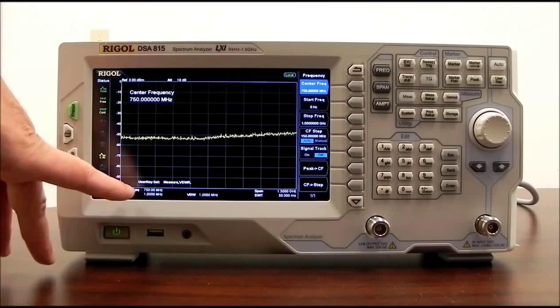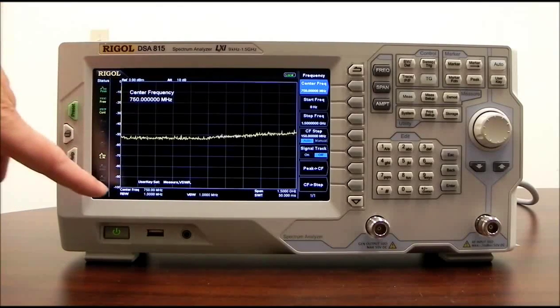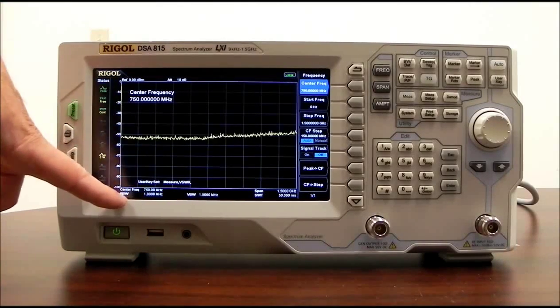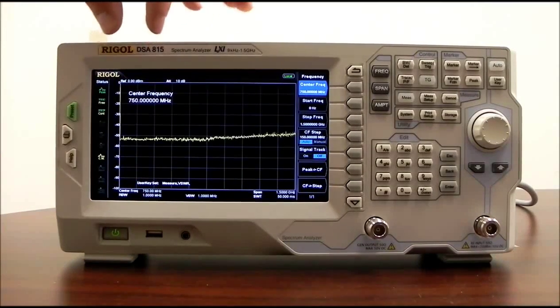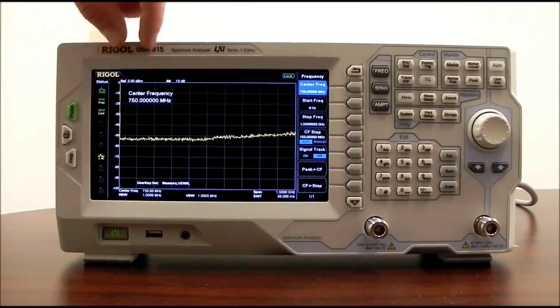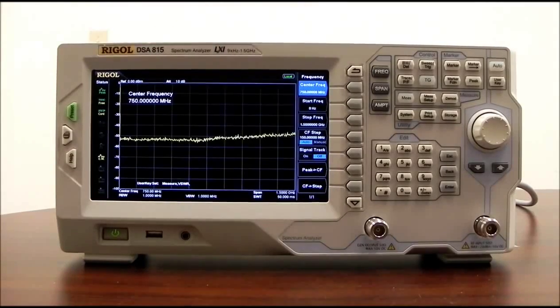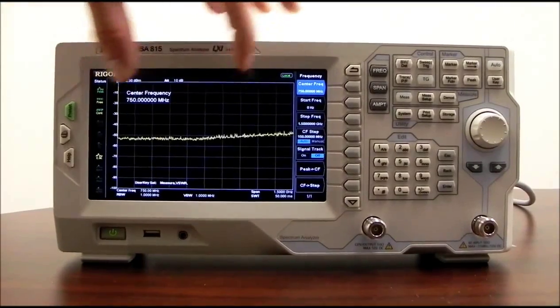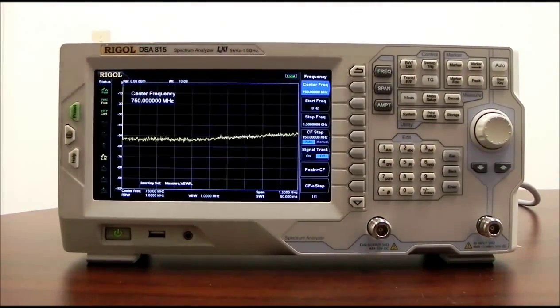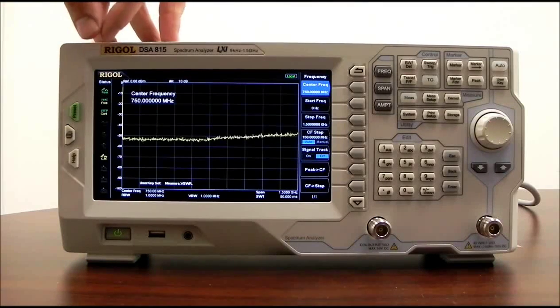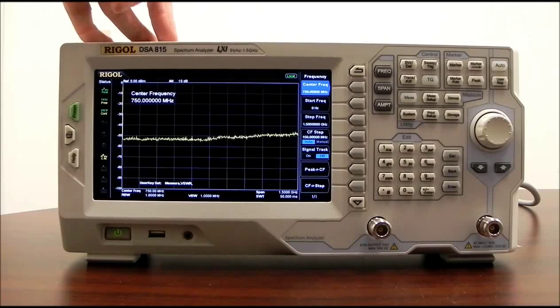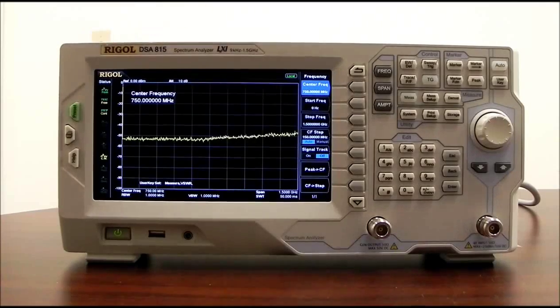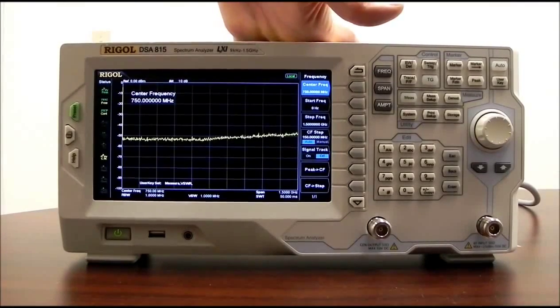So down on the bottom here, we're indicating our center frequency, 750 megahertz, and resolution bandwidth. Resolution bandwidth is the size of the detector opening that is then being scanned. The wider that resolution bandwidth, the more spectral content we're taking per frequency step as we're scanning through. So we have less resolution, but it scans more quickly. By shrinking that resolution bandwidth, we get a much higher degree of resolution, but each scan then takes longer. It's sort of the catch-22, I guess, of the spectrum analyzer.